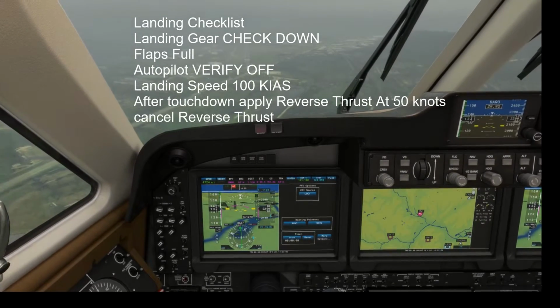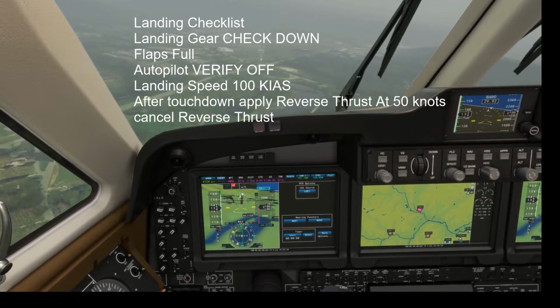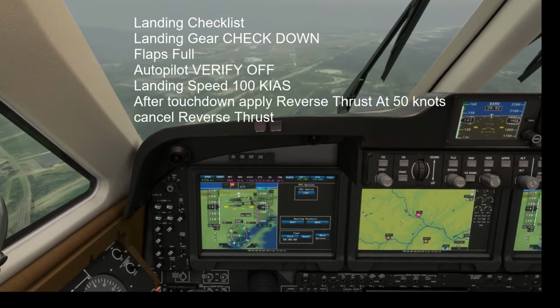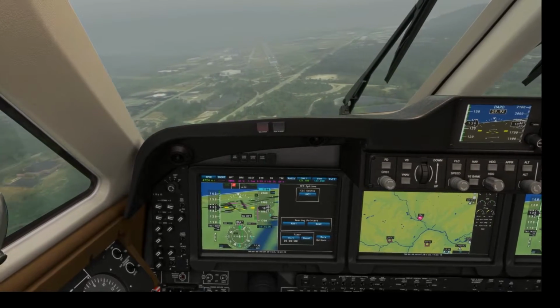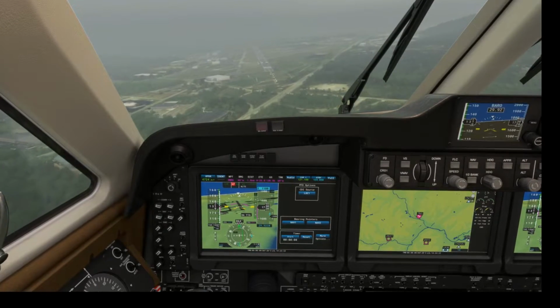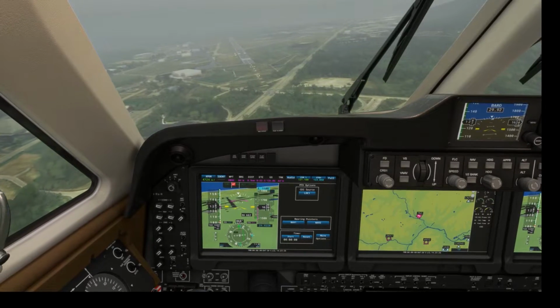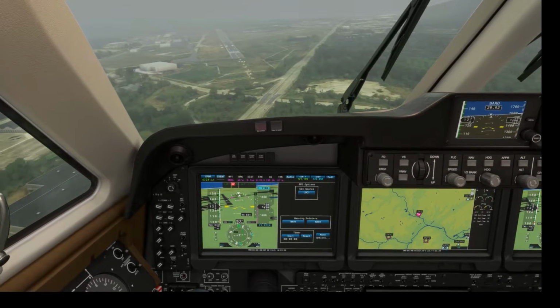Landing gear down, check. And you can put on reverse thrust if you want. This plane does have reverse thrust. You may have it programmed in. So you can see the localizer lined us up really nicely with the runway. And now I'm just going to have to do a manual approach and landing, coming in at around 3 degrees on a slope of 3 degrees.